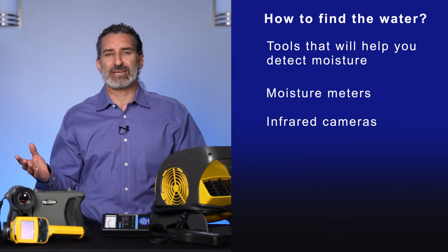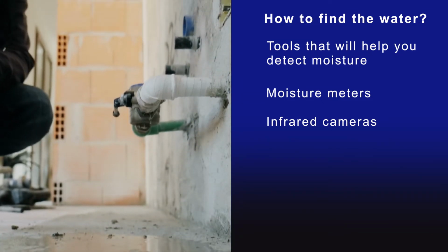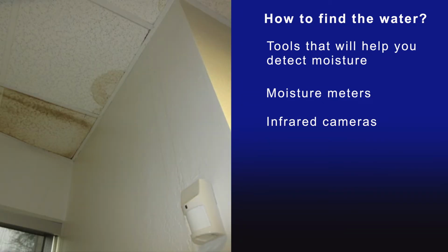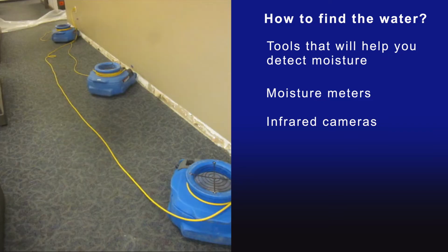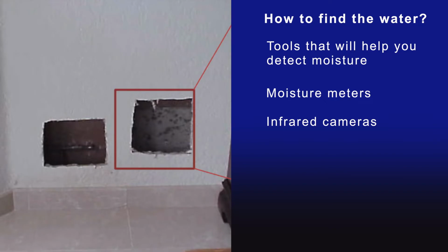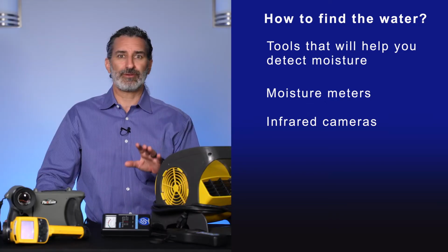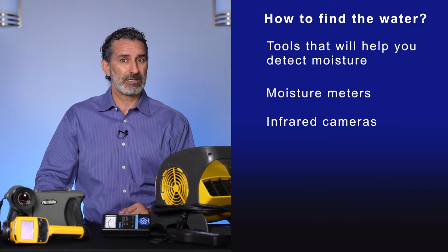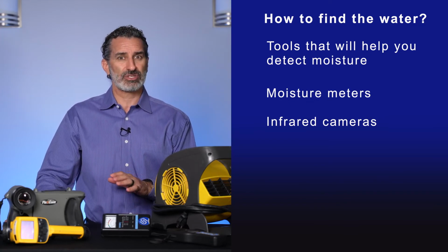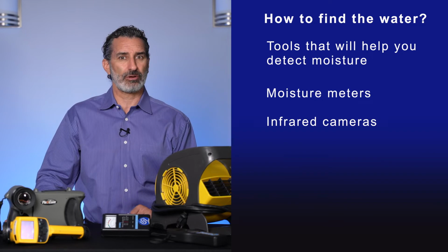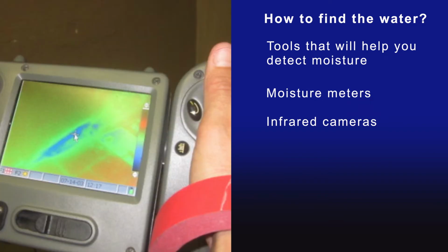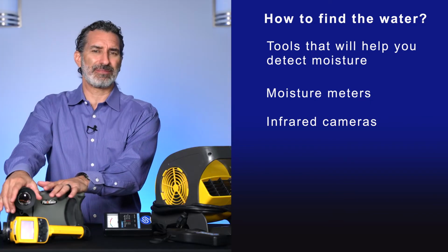Sometimes things are in standing water. They are wet. Sometimes things are water stained. They appear wet. But there are many things that can be wet that will support the growth of mold or will damage your building materials that are not obvious to the human eye or to the touch. So your professionals or maybe your in-house team should have the right tools to assess what is the footprint of this water event. Infrared cameras measure temperature difference at the surface.